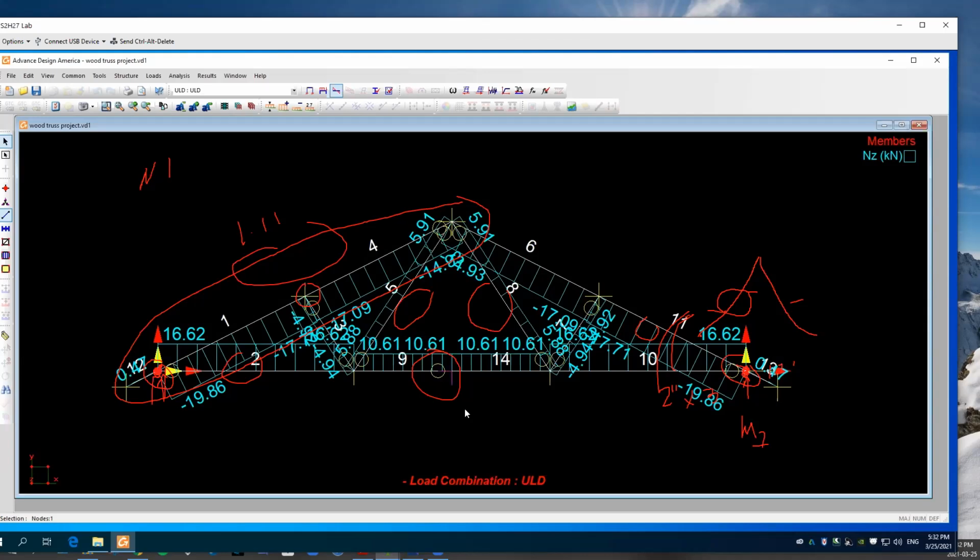I think the only thing you can actually do here is make steel HSSs that you can fit your wood in. In other words, you'd have to make a steel joint like this, out of steel, and make sure that it's strong enough, and then slip your wood inside your steel, and make sure that this is long enough so that it can develop that bending moment.